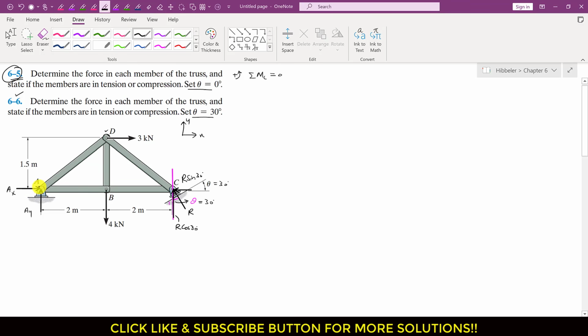So now as we can see that this AX is passing through that point C, so it will not produce the moment about that point C, right? And this AY is producing the clockwise moment about that point C. So I will write AY, and the perpendicular distance of this AY from that point C is 2 plus 2. So we can write that AY into 4, right? And it is producing clockwise moment, so we will write minus with it.